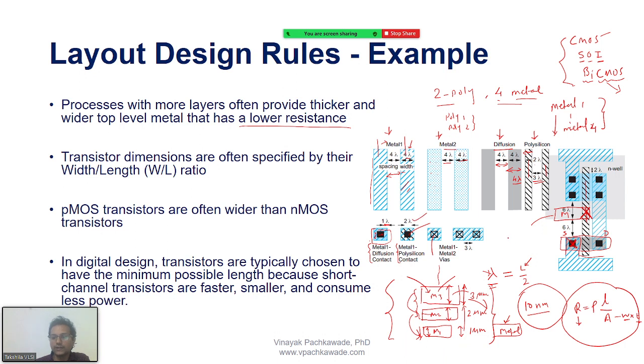What if I want to connect metal 1 here, and then on top of that I have metal 2? So I want to connect these 2 layers. There is also a question of why I should have so many metal layers, because it allows me to make a number of interconnections, right? You have so many options, so you don't overlap each other.